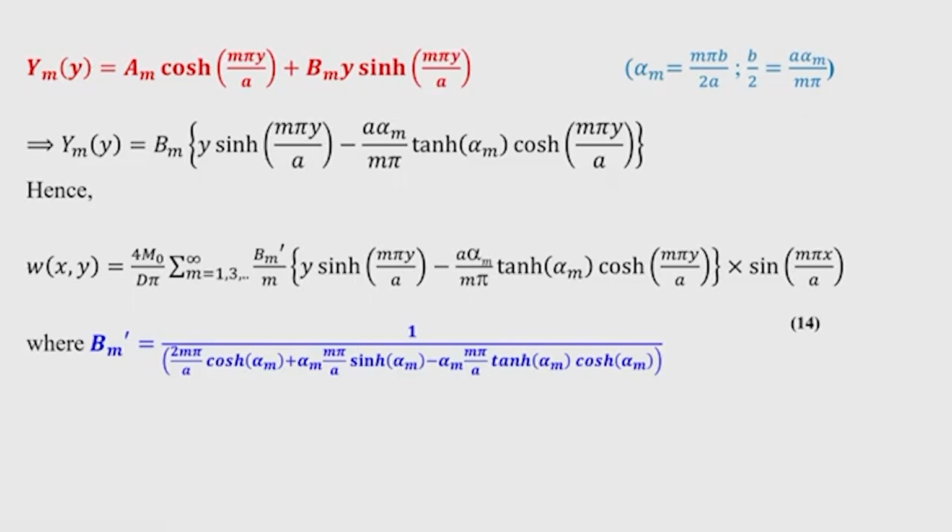In addition, you can find the corner reaction force that is developed at the corners due to the twisting moment effect on the two adjacent edges. So, this corner force will be trying to lift the plate. If the plate is not properly anchored or held down, then it will try to leave, and therefore, in the case of a simply supported plate, generally the corners are provided with an anchoring device.